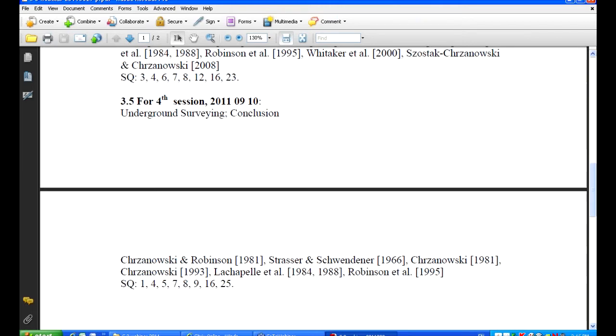So you take a reading in one campaign, a second reading, take the first one away from it, and that's delta S, a change in the distance. Then you just do the propagation, take the partial of the expression with respect to S and with respect to delta S, and what you find is that the propagation is less sensitive to the uncertainty in the overall distance because it ends up with a denominator that's S squared, because it's initially in the denominator to start with.